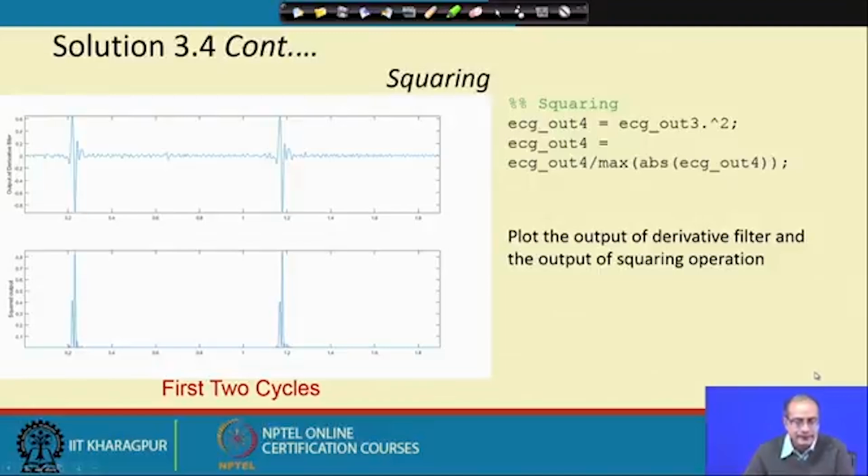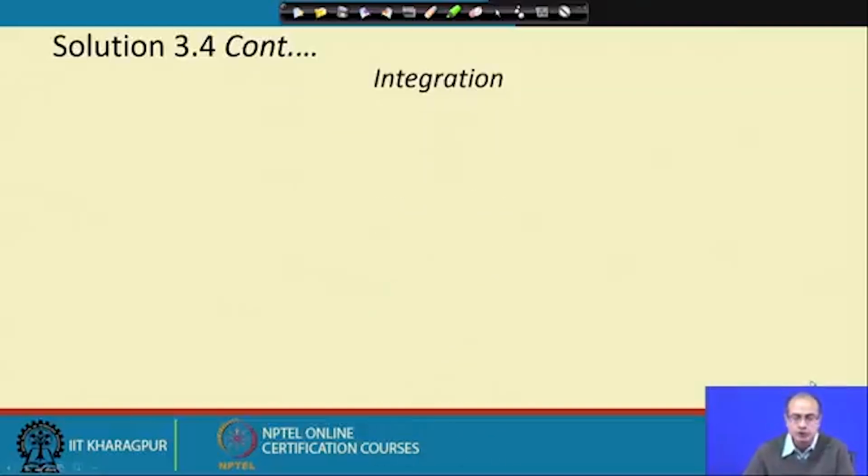We get the peak, but it is a bit jagged, multiple peaks are there. So, the question remains which one we need to take as the real representative of the QRS complex, or rather though we are sure that the QRS complex is there, which would indicate the location, we get into that dilemma. So, we go to the next step,